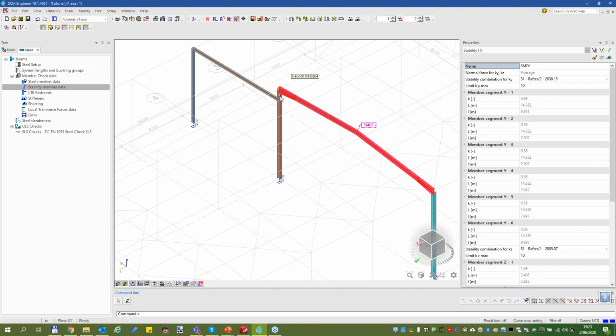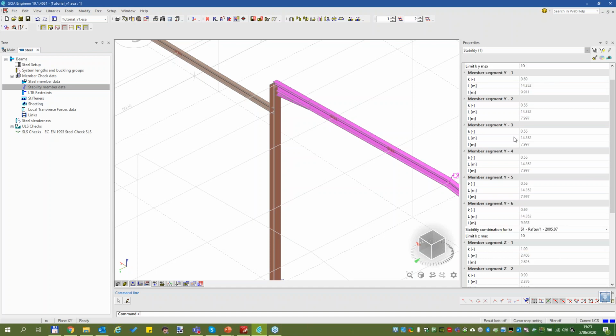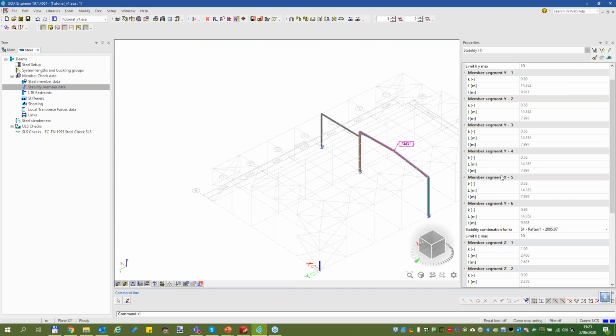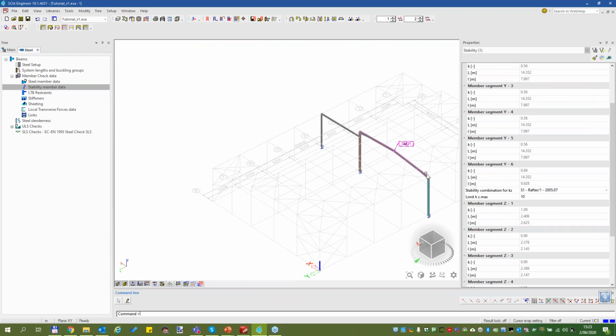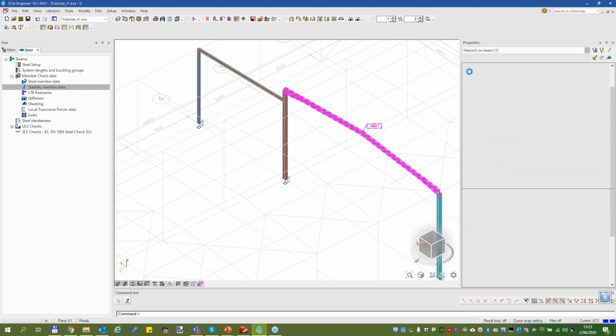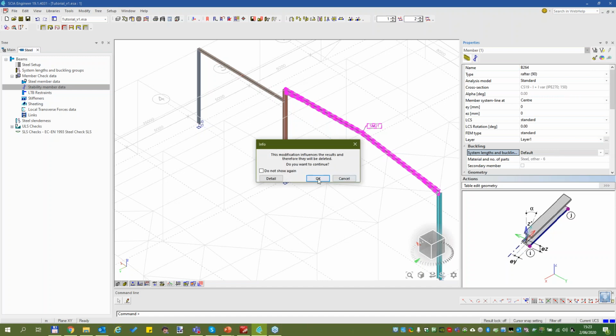This is because your cross-section is different here. You have a different IY, second moment of area, due to this variable cross-section. But here it's constant, which leads us to a constant value of the KY. And it's also one big span, so it's calculated per span. For the Z, there are multiple spans. This is, for example, span 1, span 2, span 3. Maybe I can show it a bit more clearly if I show you those spans.